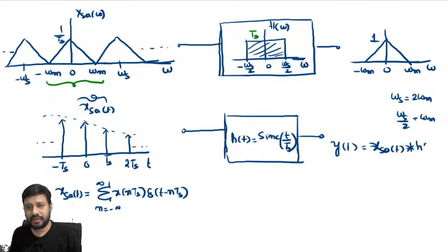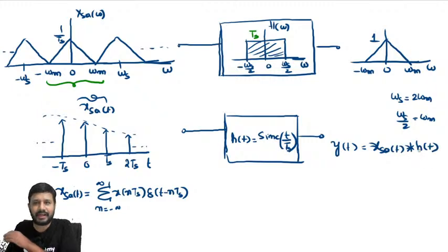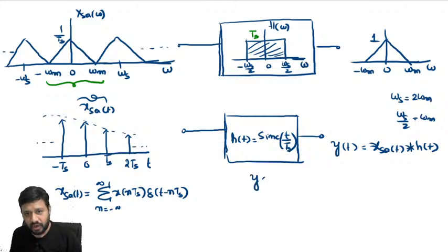See, in frequency domain, we'll say that we'll pass it through a low pass filter, we'll get the original signal back. But in time domain, how is that going to happen? How are we going to reconstruct your original signal? You must observe, right? This is an example of the input convolved with h of t. Now, input is there, impulse response is there. So output is a summation. After the class also you must verify, my dear students.